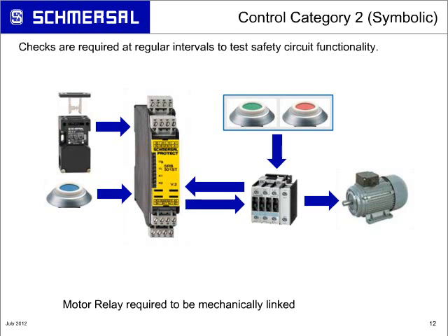Why that's important to us when we talk safety circuits is the monitoring capabilities. When a contactor fails and welds and stays shut, how do we know that that contactor has really failed? The normally closed, if it's allowed to close again, you can never detect it. But in a mechanically linked relay or contactor, because you have to maintain that gap, now you can feed that loop back into your safety monitoring relay.